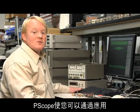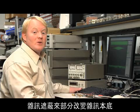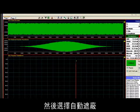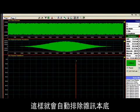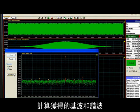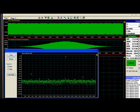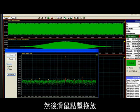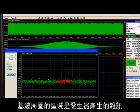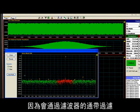PScope allows you to change what is considered part of the noise floor by applying a noise mask. This is done by selecting this button on the toolbar. Then selecting Auto Mask. This automatically excludes the fundamental and harmonics from the noise floor calculation. Then mask by using the mouse to click and drag over any area you want to exclude from the noise measurement.